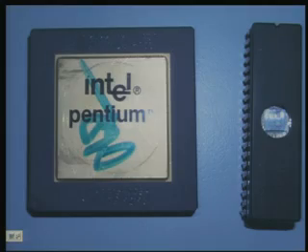So, here for example, you have two different CPUs. This one on the left is a Pentium processor, and one on the right is again from Intel, same manufacturer, but a microcontroller. So, it is this type of processor which is found typically in embedded applications. The actual chip is this small rectangular piece which you see inside this circular window, whereas in this case the actual chip is of that size, this big square which you see.